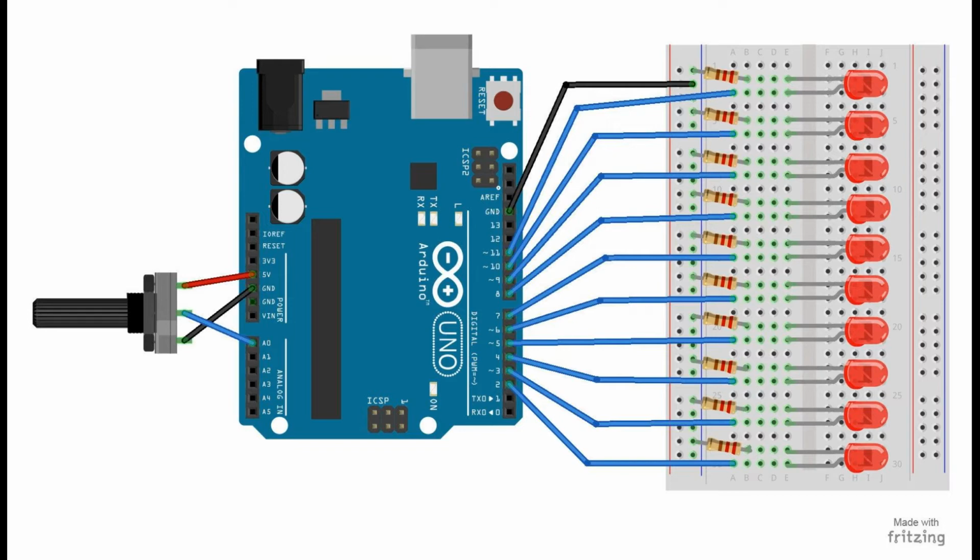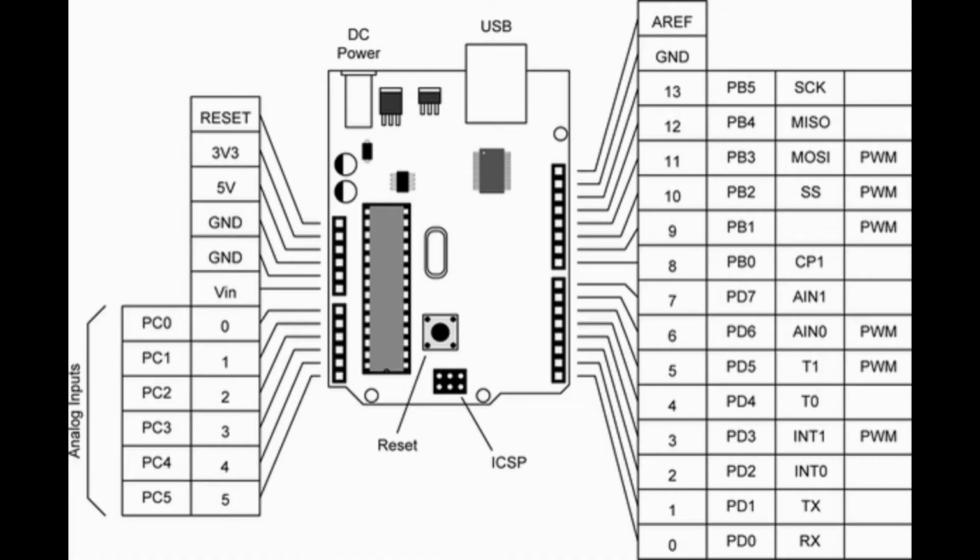How to use Arduino board. The 14 digital input-output pins can be used as input or output pins by using pinMode, digitalRead and digitalWrite functions in Arduino programming. Each pin operates at 5V and can provide or receive a maximum of 40 mA current, and has an internal pull-up resistor of 20-50 kilohms, which is disconnected by default.